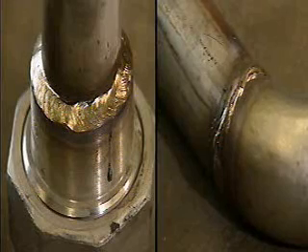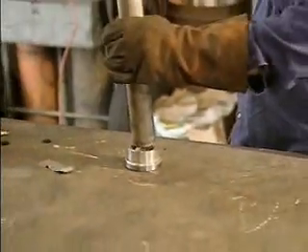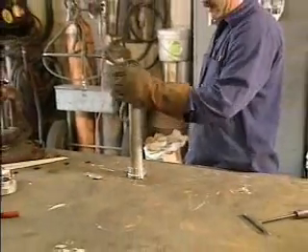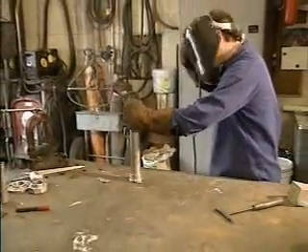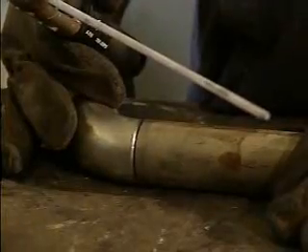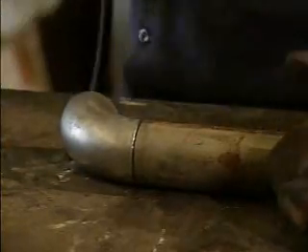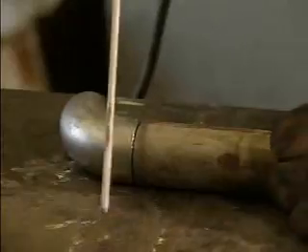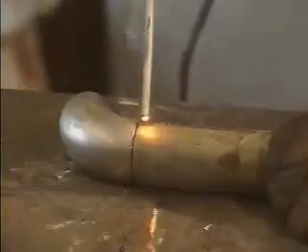There are two types of welded pipe joints, socket weld and butt weld. In a socket weld joint, a pipe is inserted into the socket of a fitting that has an opening larger than the pipe's outside diameter. The edges of the socket are then welded around the outside of the pipe. To create a butt weld joint, the beveled end of a fitting is lined up with a pipe. Then the edges of the joint are welded around the outside of the pipe.